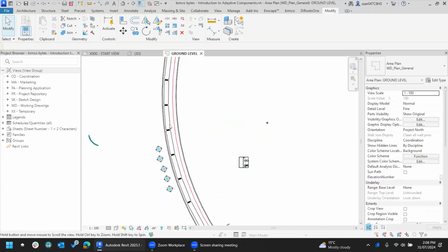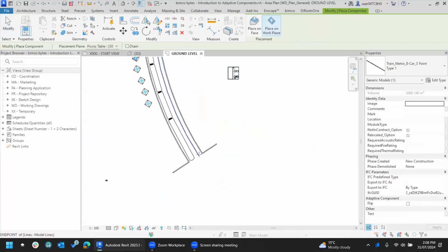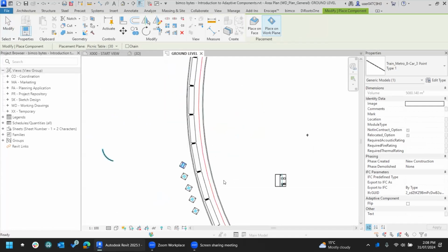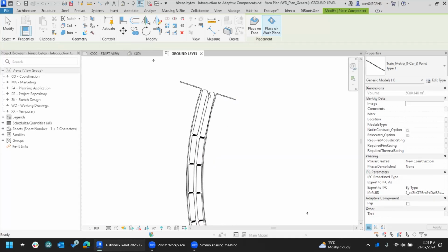So there are multiple ways that you can place families. In this case, I'm actually doing the midpoint second and not last, unlike the curtain. So first click there. Coming in for my second click here, somewhere around the middle, we'll estimate. And the third point's actually going to be the end point. So these are all settings that you can determine when you're creating your family, the clicking order. All right, so you can see a little preview there. And that's much better.